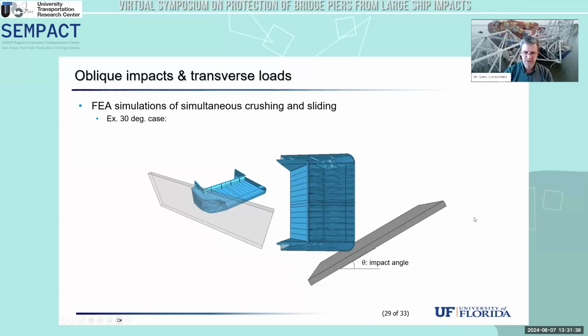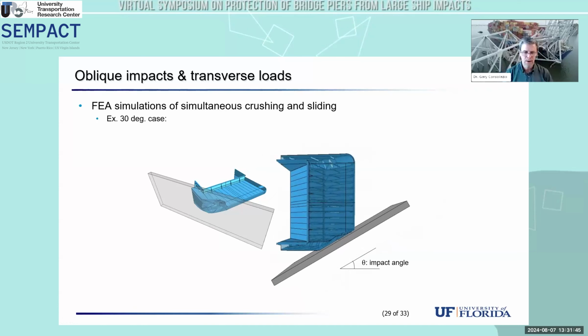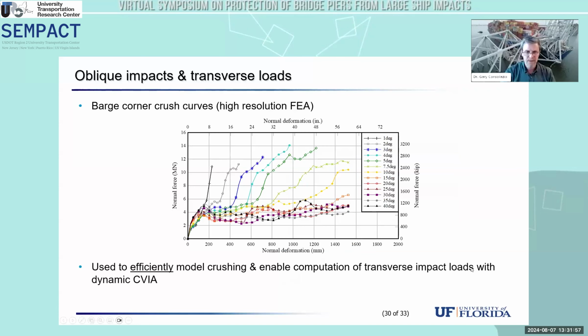So how do we generate those spring curves? Well, once again, we turn back to advanced FEA, or a fairly high resolution FEA as opposed to low order. We do a crush simulation, a corner crush simulation, as I'm showing here. We monitor the normal deformations and the corresponding forces, and pairing those two up, we get a crush curve. We get a nonlinear crush curve.